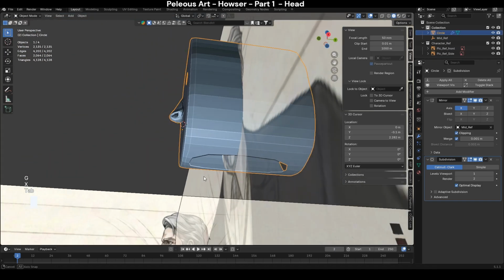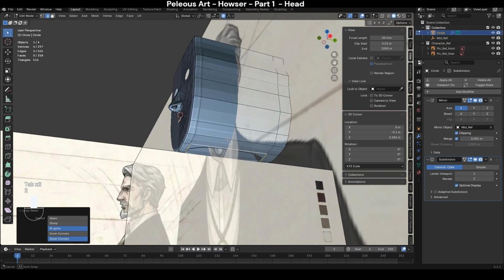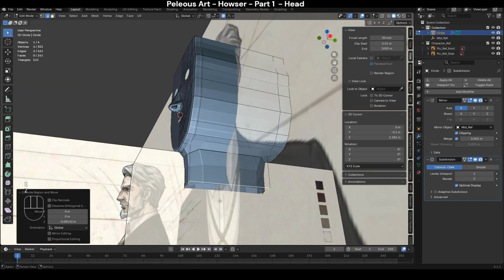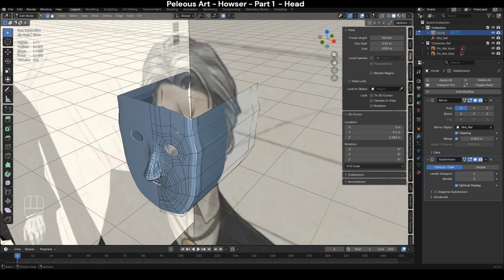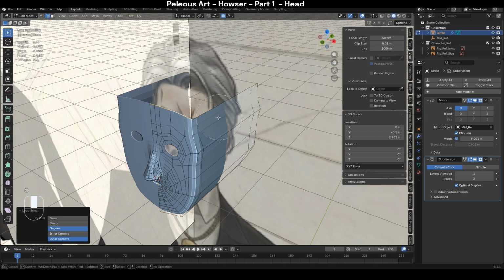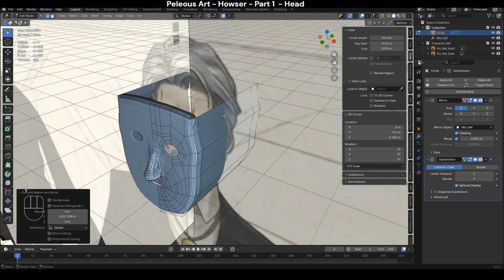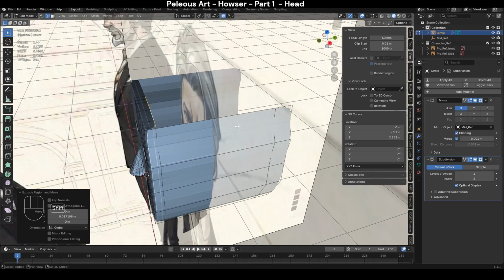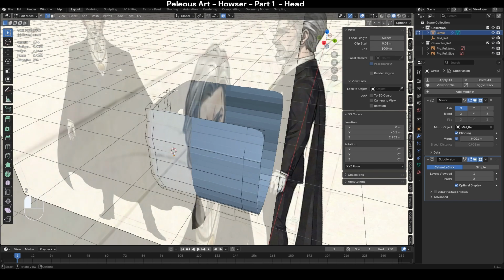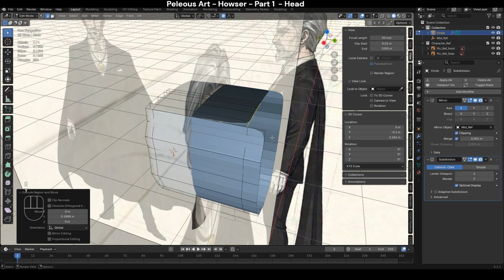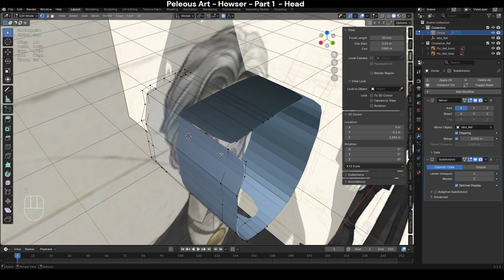Now with Alt we can select and E to extrude. Okay, we're not doing it now, I'm just demonstrating. Let's ensure all the rest will be connected properly. So E to extrude with the merge on. Okay, let's turn on the merge, or we can select the vertices and M, merge at center, whatever you prefer. Deselect with the middle mouse wheel, carry on, extrude, connect it. Okay, so M, merge at center.